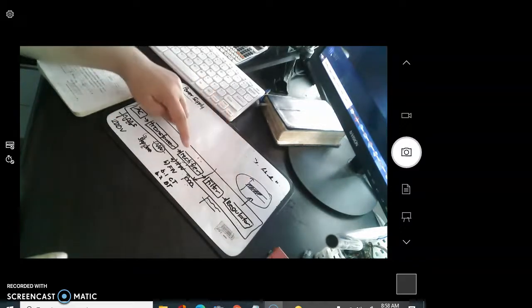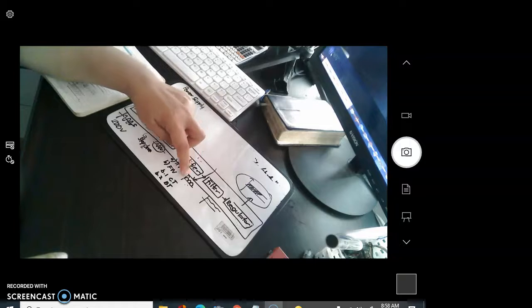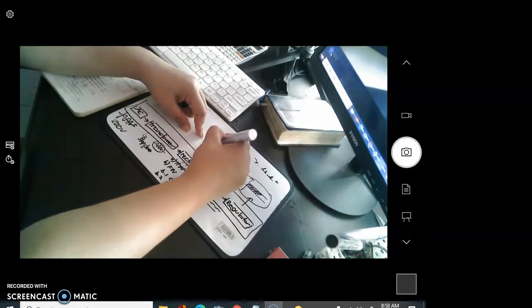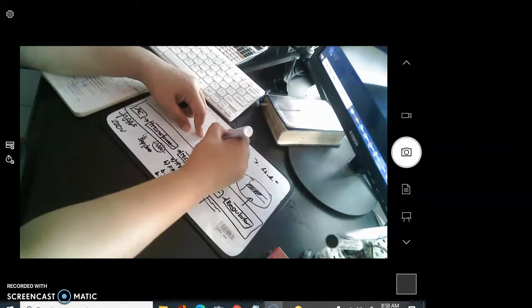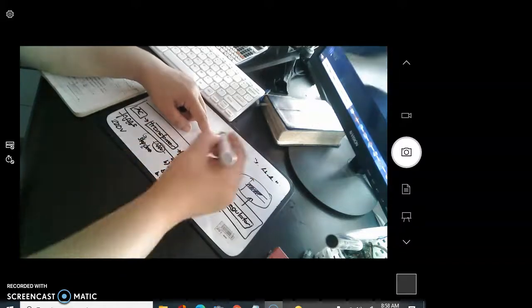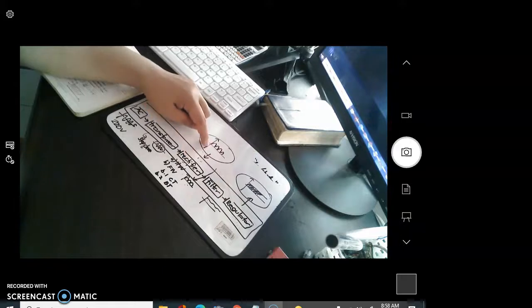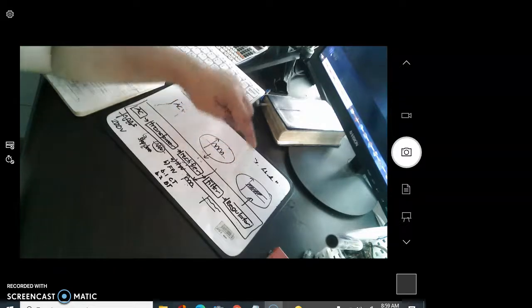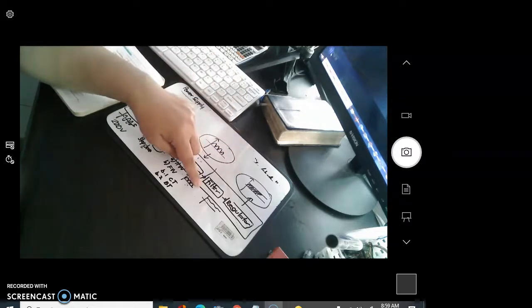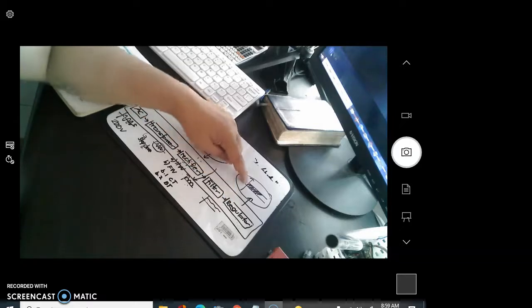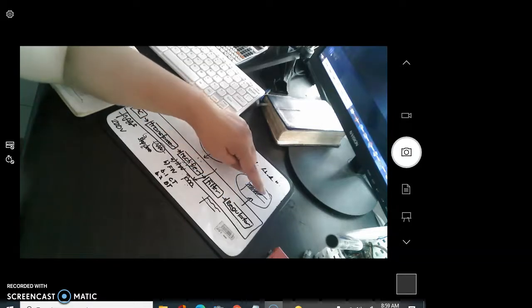Take note, for the rectifier, the output is already DC. The output of the rectifier is already DC, only pulsating. This is already a DC. So this is the output of a rectifier. It is already a pulsating DC, but not the desired. The desired DC is a flat one. So it has to pass through a filter to smoothen it, and it has to pass through a regulator to regulate the voltage to a stable value.